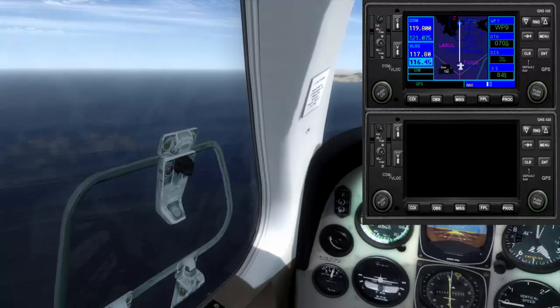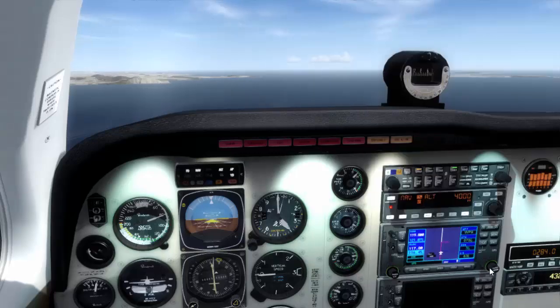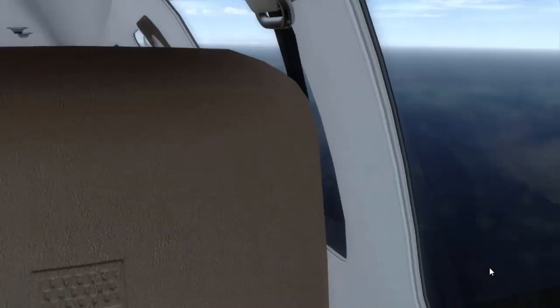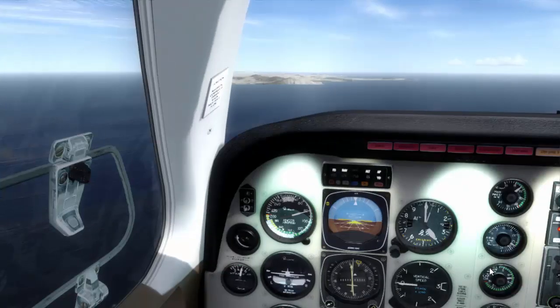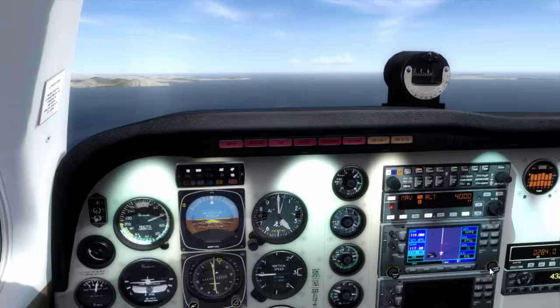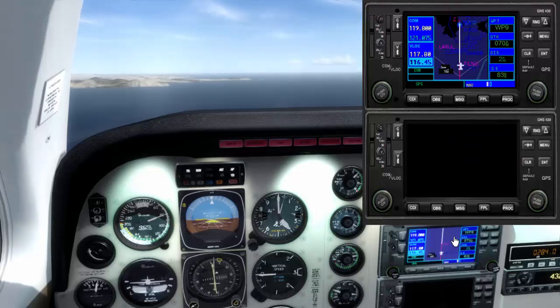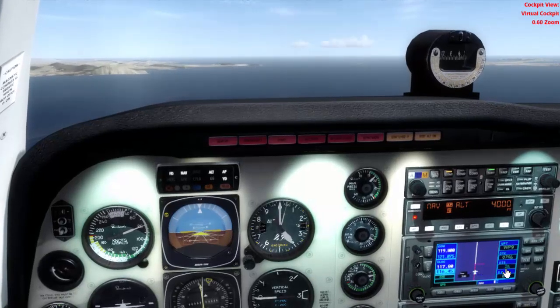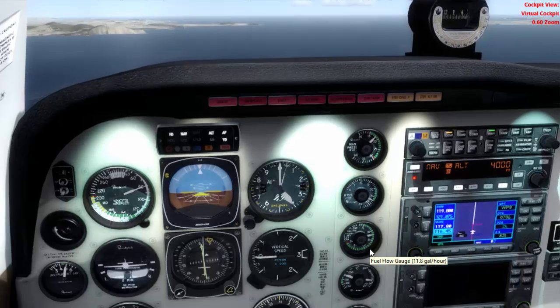When we reach Tilno, we will depart following our own heading, our own radial, and that will be 085 degrees, as it was indicated in the instrument approach chart. And if I remember correctly, Tilno is also indicated in the STAR chart as the initial approach fix. Basically, the STAR chart is very easy to understand. It indicates only one point, whilst in the instrument approach chart we have a lot of different points, procedures to follow, descent rates, and every single thing. So the STAR chart is a chart that you can finish in seconds. Just one point and you're done.